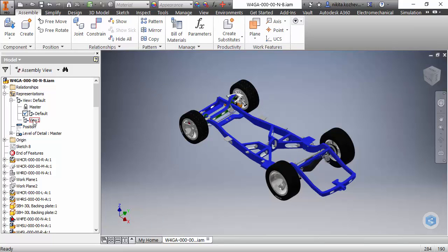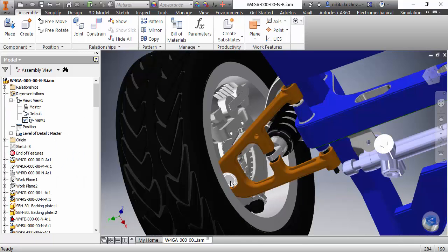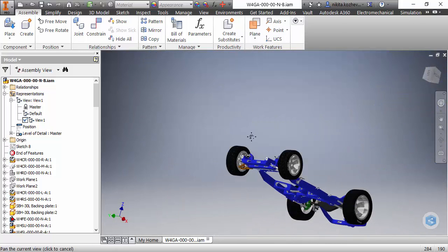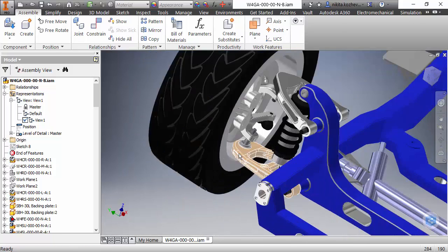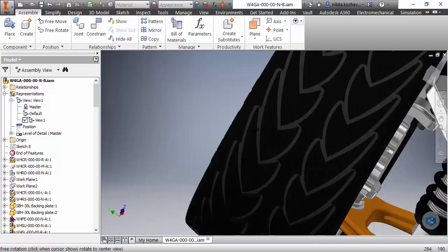So as you can see, that part is pretty important because it takes all the weight, or basically a fraction of the weight of the car, and in this particular mechanism takes the vertical load through the steel insert we've got here and the connection to the wheel through this ball joint.